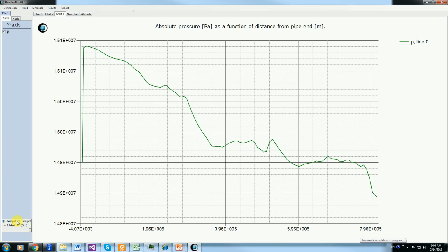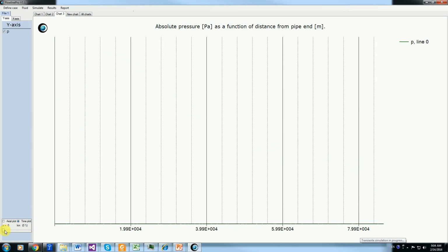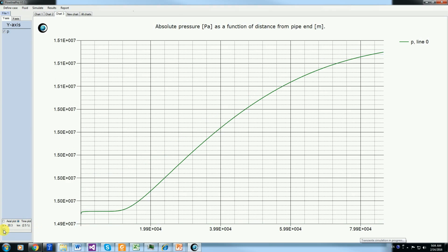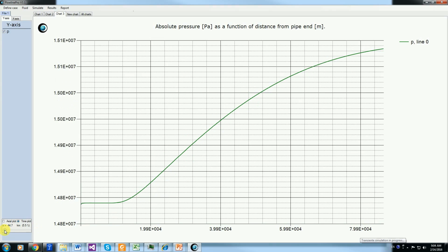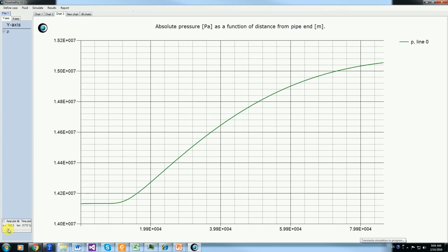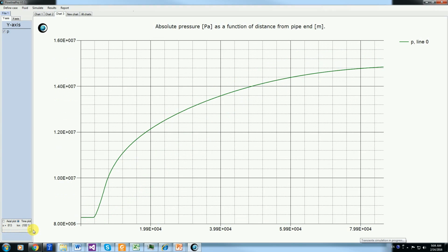We can also make a time plot here. So at the beginning there is no change over time at the inlet, because we kept the pressure there constant. But if we go into the pipe, now we are 44 kilometers into it and so on, and we can go to the very outer end. This is a time plot of the pressure near the outlet end. Remember, for 1 hour we kept it fully open, then we closed it, and the result of that we see is a gradual increase in the pressure near the outlet.